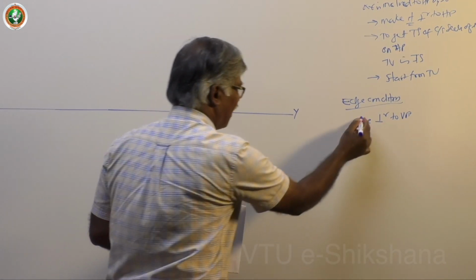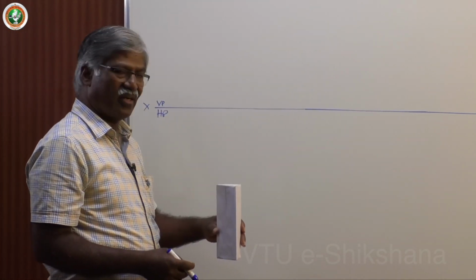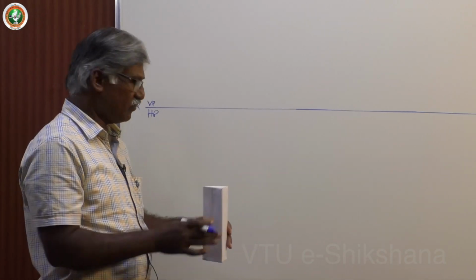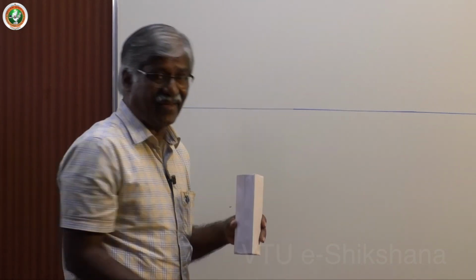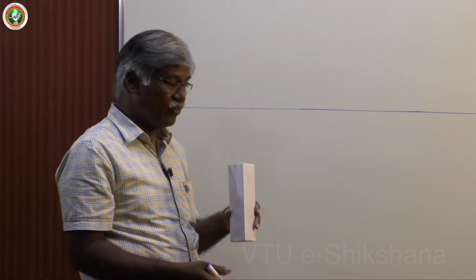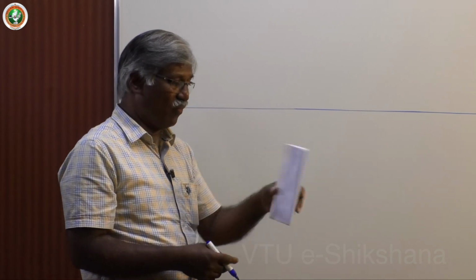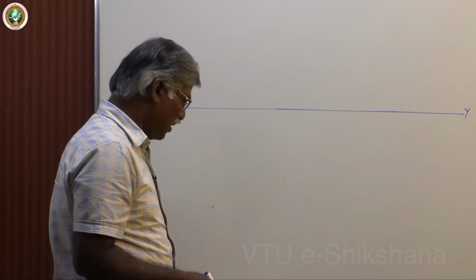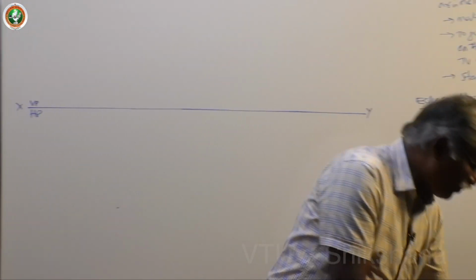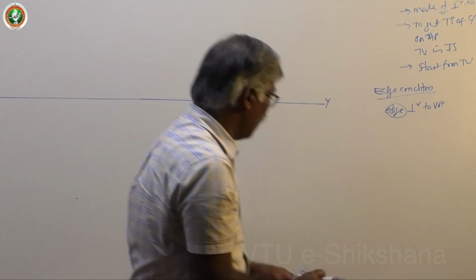What edge? Already I told you, the edge to be placed on HP. Now this is the initial condition, first position, so the axis is perpendicular to HP. Always you prefer to take it to the right side. For laminae we used to take it to the left side for space management. Here it is going forward, so it is to be taken to the right side. So naturally the initial position is a triangle of the size equal to 35 mm.